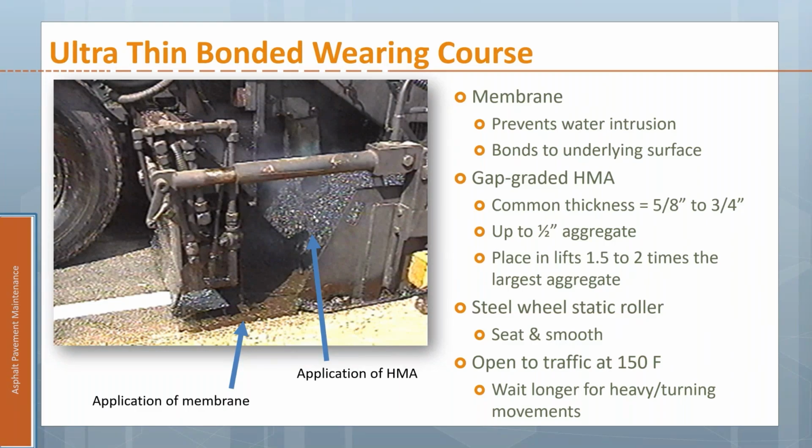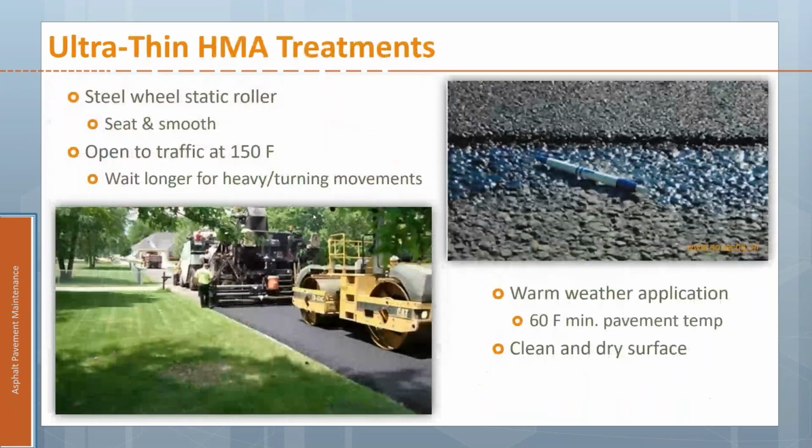I will say that you should wait longer if you have a lot of big trucks, heavy vehicles, a lot of turning movements. There was one place locally, and it worked great everywhere except right by a truck stop. And so when those trucks came out of that gas station, got over to the light, then they were starting with that heavy load and making a turning movement across the new pavement. That was where there were some places where the surface would tear when they let the trucks on it too early. So that would be my one caution.